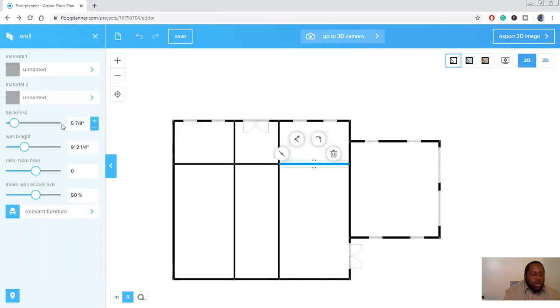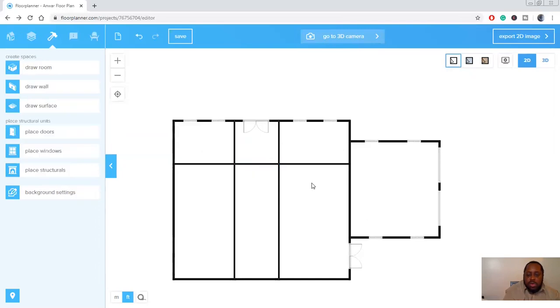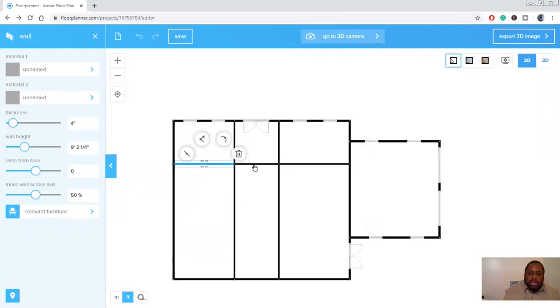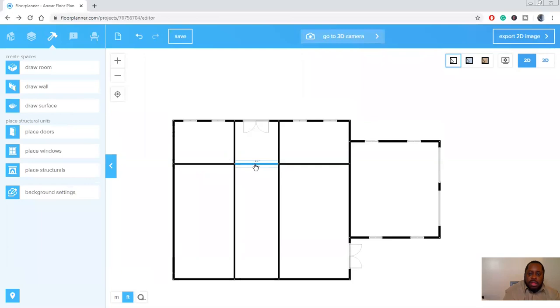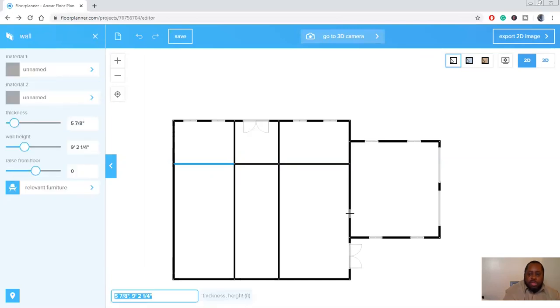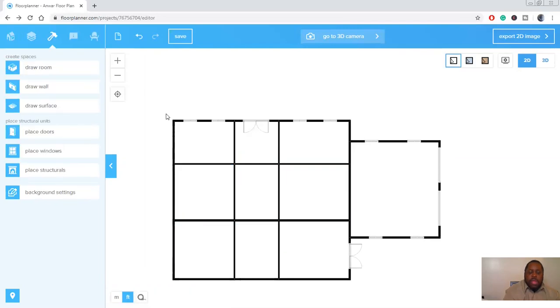So right now, I'm just changing all the interior walls to be consistent. I can take that same wall information, hold down Shift, and grab one at a time. And let's do this instead to make it easier. Grab another wall, draw another wall, same thing, bring it across. And if you have that line that goes across the screen after you draw a line, just hit escape. That's all you have to do, just hit escape.